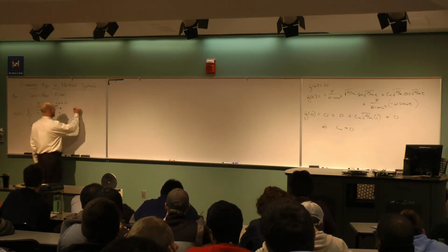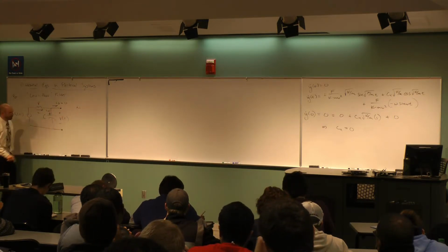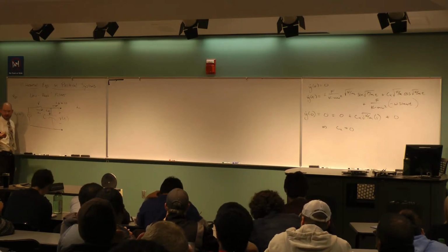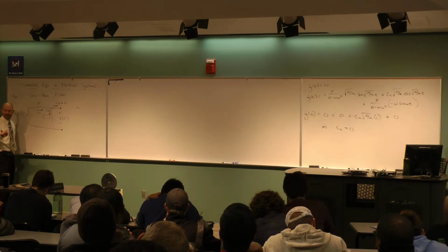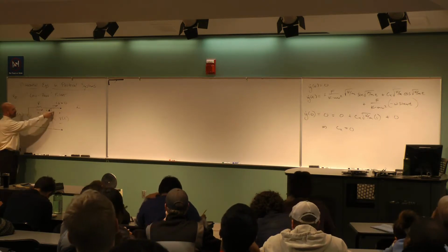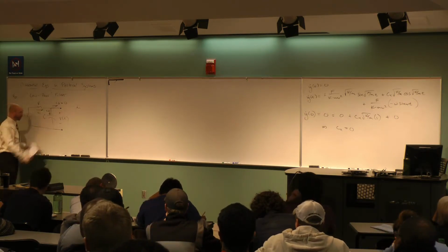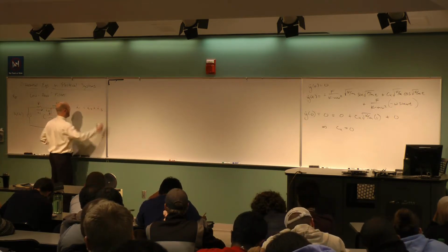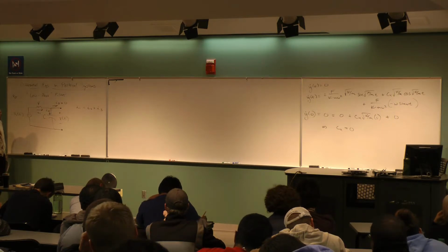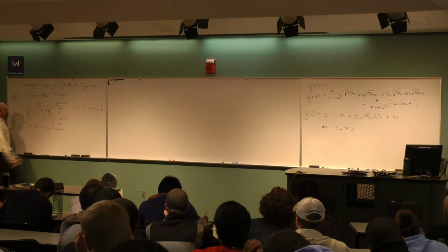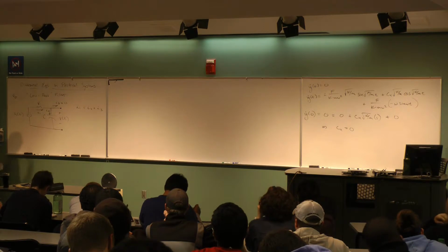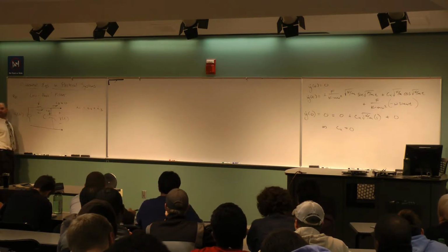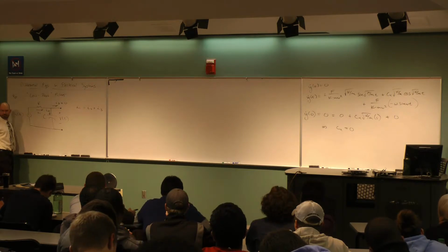Here's the argument. This is like volume flow. Current is actual flow of electrons, right? So conservation of mass applies here. Whatever I1 is, if it hits an intersection, it has to be equal to the sum of the other two. So I can say I1 is I2 plus I3. That's a true statement. And then I can begin to identify what each of these currents is based on my governing laws. So for example, across a resistor, I get a voltage drop V equals IR.